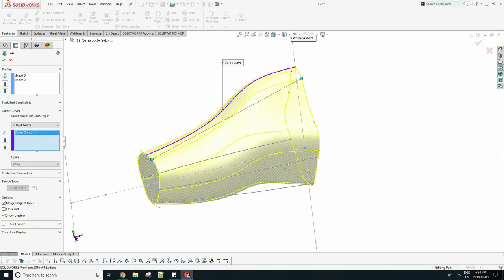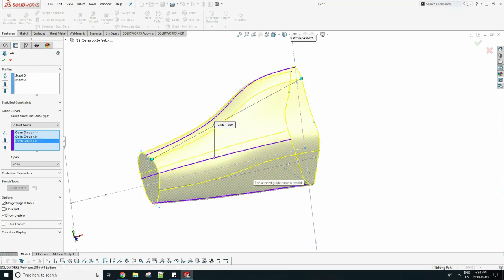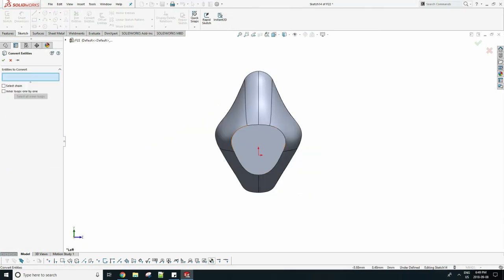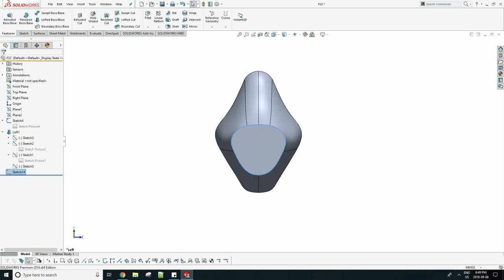When that's done, you can then do a loft. So go in the loft feature and click the 2 profiles and then do a loft curve. So that looks extremely well. It looks essentially almost like the actual airplane, but now we need to do some sketches to complete the nose cone. So let's first do convert entities